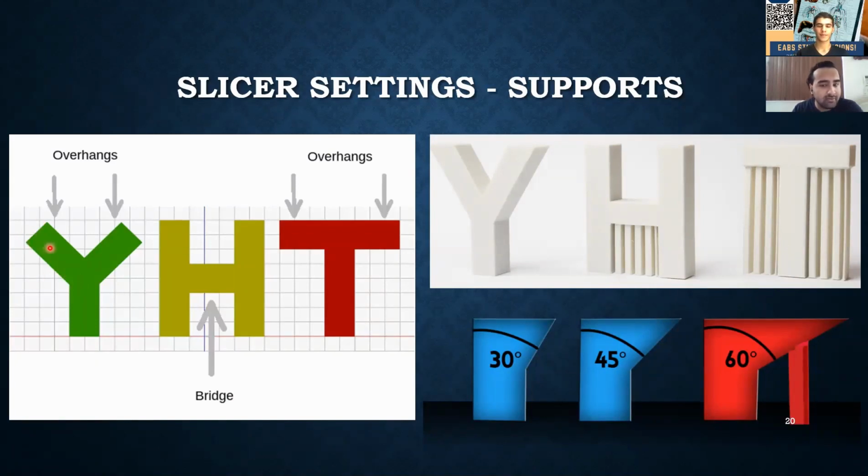Now, how much of an overhang you're allowed to have varies, but generally a good rule is 45 degrees. So you have any sort of feature in your model that is more than 45 degrees, I would consider removing it. But if it's less than 45 degrees, generally you can get away with just leaving that there because you can do a strut print here. Then the next layer sort of has enough of the layer below it to support itself, and then you can get away with doing the overhang.